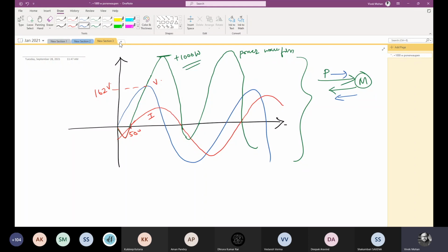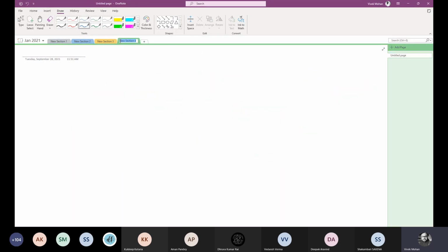And you can see from the signal that for very less time only power is flowing out of the motor, right? The direction is reversed only for a very short time period. Now the voltage, current and instantaneous power, when we plotted these things, the power attains a positive peak. We have seen that it happens at 1000 watts, and I have a negative peak also. So this is my positive peak. I have a negative peak also for power, that is happening at maybe minus 218 watts.